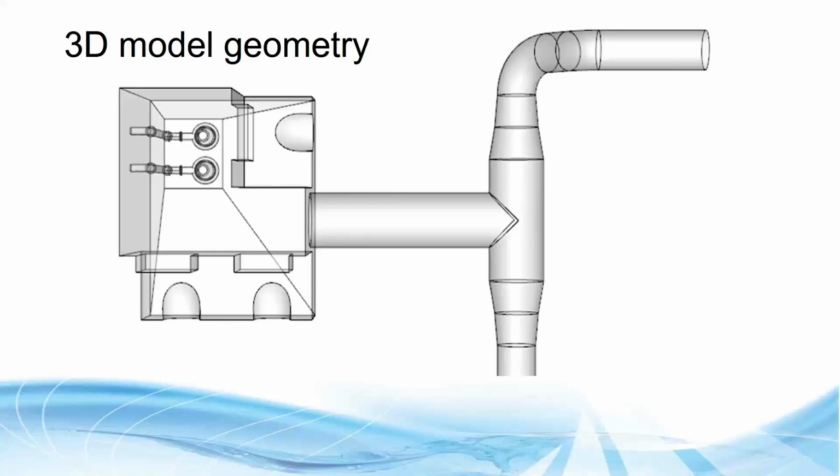Now you might be wondering why there are 2 pumps within the chamber. It is a distribution chamber, but that's because this is an existing structure on site. It is currently used as a RAS return, so water enters the station and is then pumped out. Now, to try and reduce costs and time, and make sure that they don't have to build any new structures, they can repurpose this as a distribution chamber.